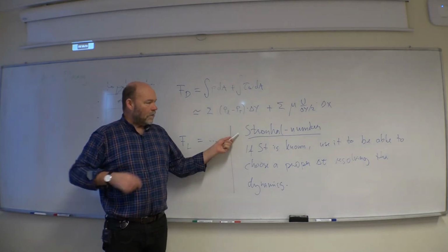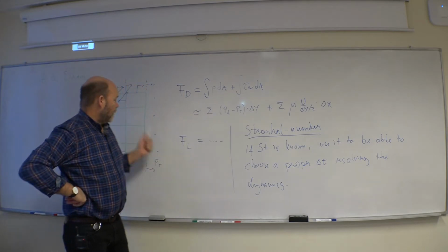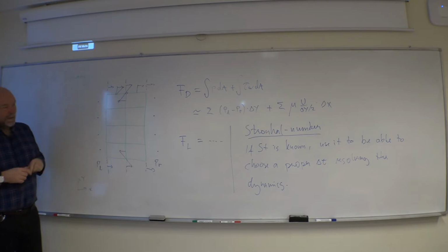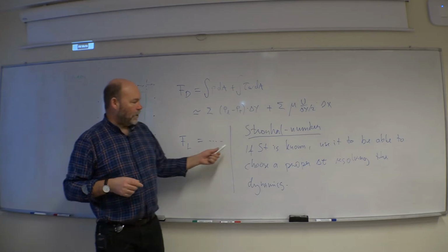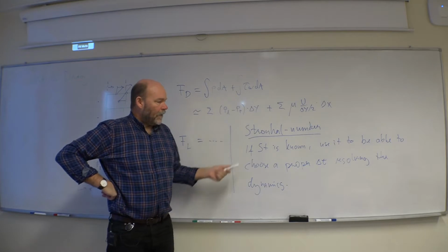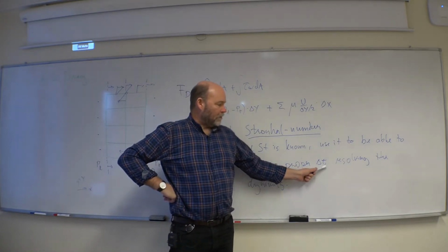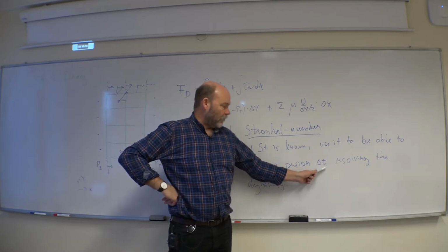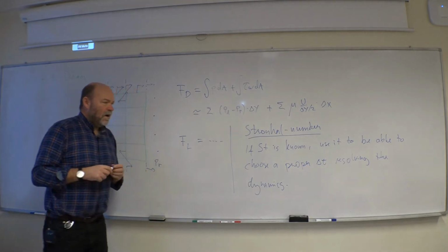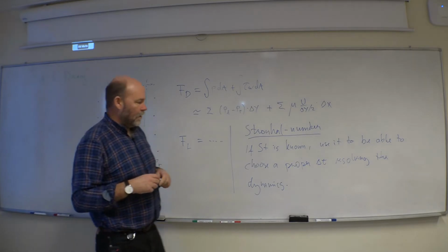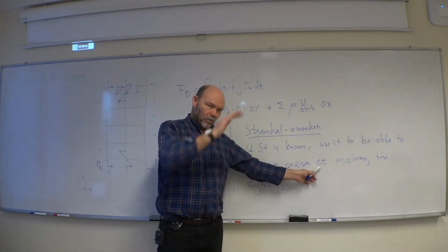But the Strouhal number, this dynamics is born from the nonlinearities in the Navier-Stokes. So this built-in frequency from Mother Nature, we have really no idea. But if we could look up the Strouhal number in advance, then we know what time scale these motions are performing about, how long time they take, and then we can better choose a nice delta t that can resolve this motion.